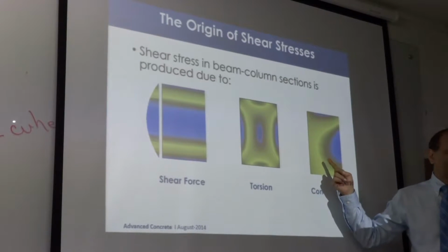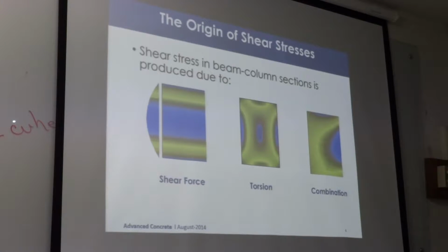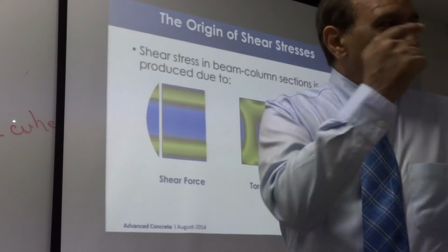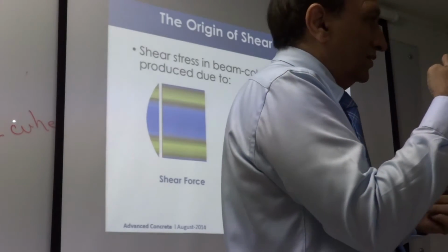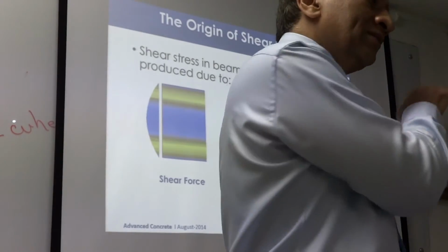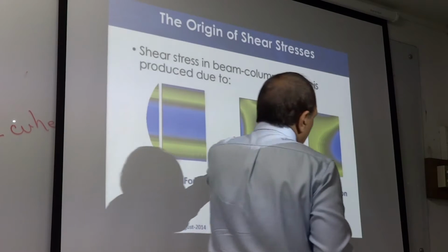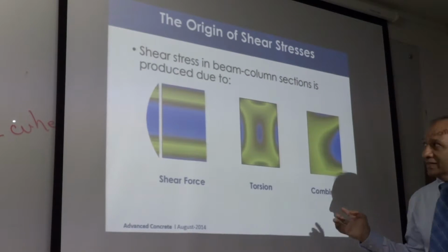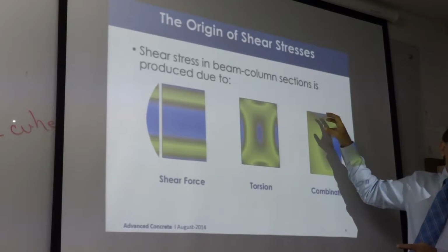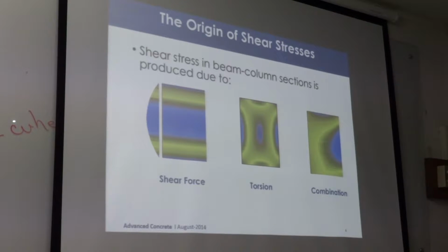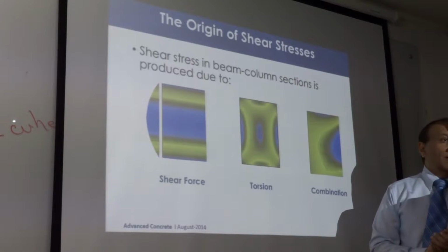And torsion has another problem. Torsion has a direct interaction with moment, because torsion produces another property I told you last time: warping. And warping is axial also, because warping has raised to power 6. 4 parts coming from torsion, 2 parts coming from bending. So that means torsion is connected to bending, and torsion is connected to shear. So shear is connected to bending indirectly. Correct? Through torsion. So now we have this whole interaction happening. That's why we need to separate this problem and try to solve it one by one.